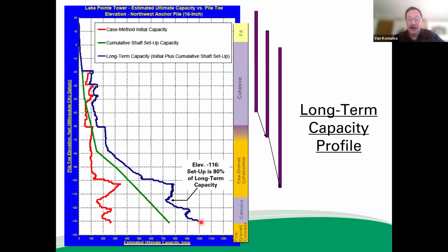And that point right there corresponds to a given blow count at a given depth. So if you go to design for that and you're driving your production piles and you get that blow count at a higher elevation, you get that blow count up here somewhere.